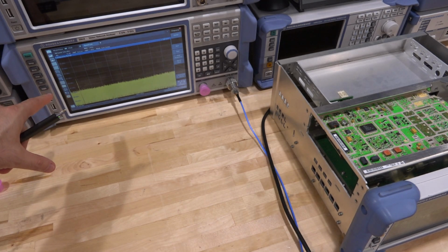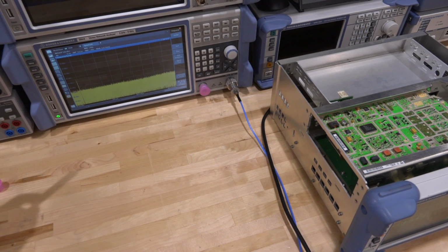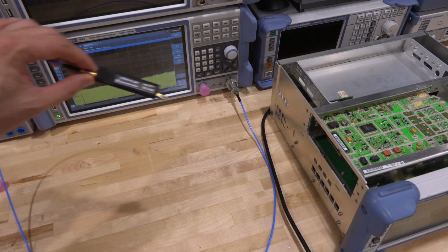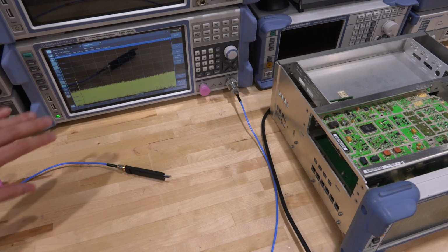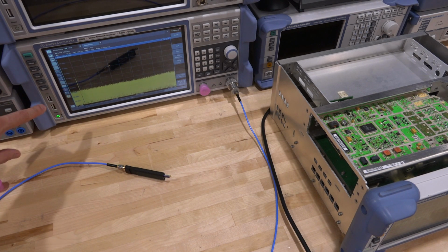We're going to combine that with the Rohde & Schwarz ZNL6, which is a hybrid instrument. I've also done a complete teardown and review of that instrument. With this ground signal tip, we're going to monitor different voltages along the signal flow and see what happens to the PLL in its operation. So I'm going to zoom in here. Look at this tone over here. That tone is from my wireless microphone being picked up.